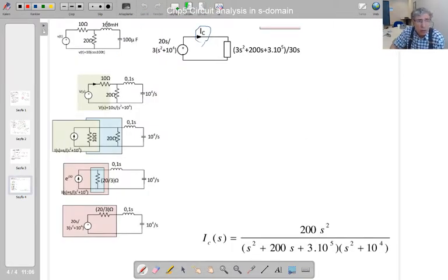Here you are. This time domain circuit has been examined for serial parallel connection example previously. So this is the S domain circuit corresponding to this given here. Now what we are saying here, we will be doing source transformation for the analysis of this circuit. How we are going to do it? See that green area here, there is an independent voltage source in serial with a resistor here, 10 ohm. So you can replace those two by using the source transformation with that green here.